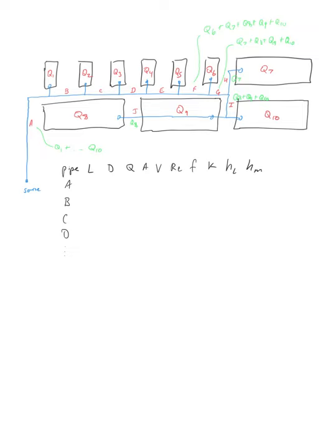When I'm looking at head loss, if I want to say, hey, what's the head loss in pipe A, for example, once I have L, D, f, V, I can use the Darcy-Weisbach equation, f L over D, V squared over 2g, to calculate h sub L. If I then add my minor losses in, I could have another column that says, what's the total head loss within that pipe segment?